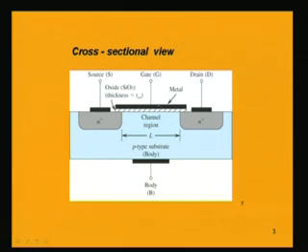Here this is the gate electrode and this is the source, and in between them there is this oxide layer. Similarly, this oxide layer is extending, so it is forming a parallel plate capacitor between the gate and the channel. The channel has these three regions: drain, source and the body itself.